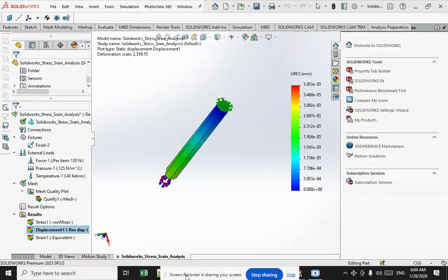While yielding of material or the structure could render the structure unusable, it would not necessarily lead to the collapse of the structure. The factor of safety on ultimate tensile strength is to prevent sudden fracture and collapse, which would result in greater economic loss and possible loss of life.